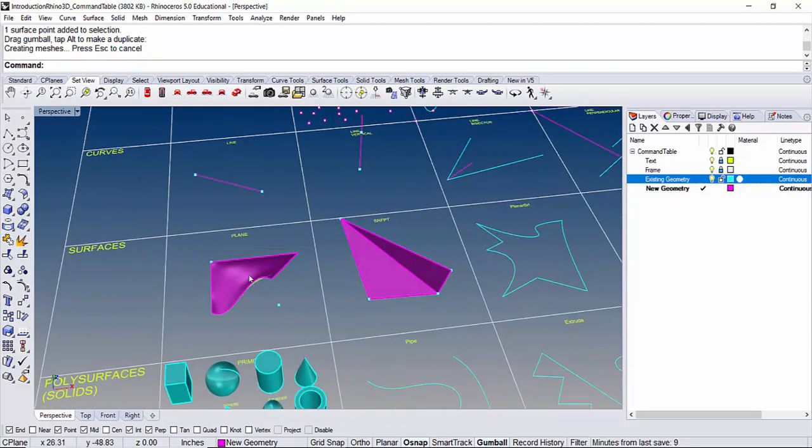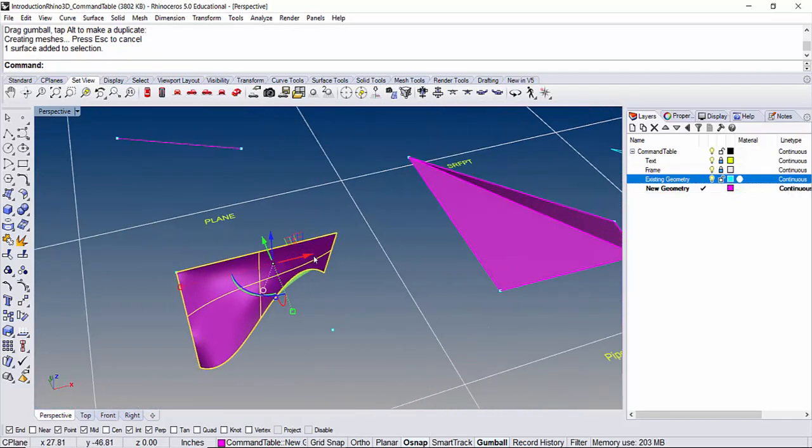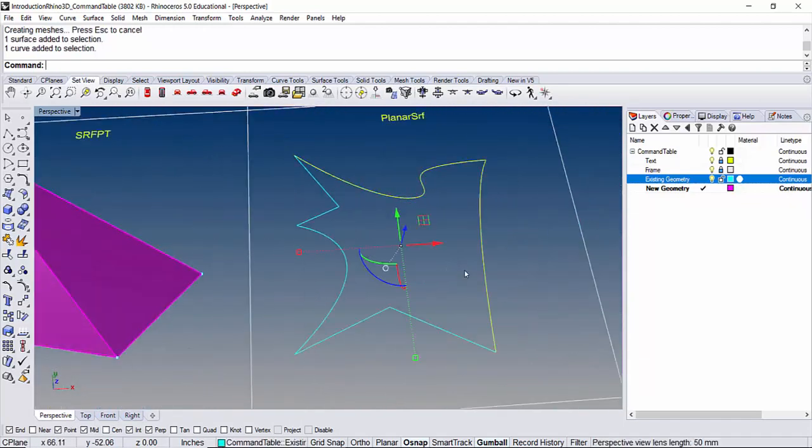So in Rhino, when you are making a surface, you at least need to have 4 sides or 3 sides for you to create a surface. So therefore, if I want to create a shape that is, imagine a surface that's filling all of this geometry, it doesn't exist. So this is a too complex of a geometry. So what Rhino is going to do is going to create a straight surface, which is a little bit outside of this boundary. Then it's going to trim it based on this boundary.